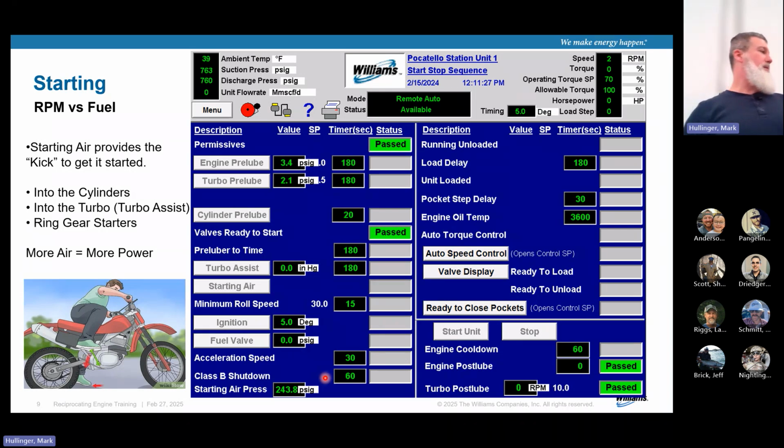So now you're combusting. This is going up and down, and you're starting to produce heat. When you produce heat, the exhaust goes where? To the turbo. And when I say turbocharger, there's a hot side and a cold side. The hot side of the turbo spins a wheel, and connected to that is the air side. So this is the air intake, and it starts to suck in air that goes into your power cylinder, and then you are sustaining combustion. Okay. So that's how that works.